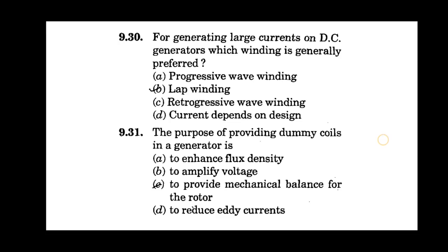The material for commutator brushes is generally carbon. The insulating material used between the commutator segments is normally mica. In a DC generator, if P is the number of poles and N is the RPM of the rotor, then the frequency of magnetic reversal will be NP over 120.